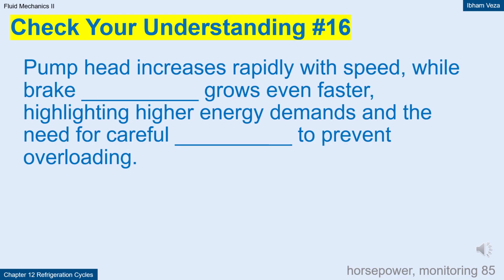Pump head increases rapidly with speed, while brake horsepower grows even faster, highlighting higher energy demands and the need for careful monitoring to prevent overloading.